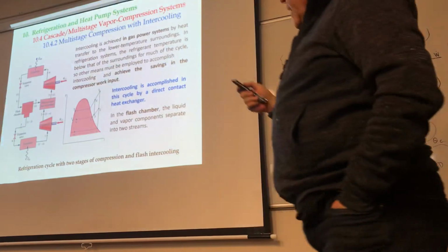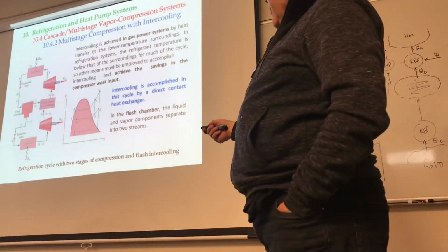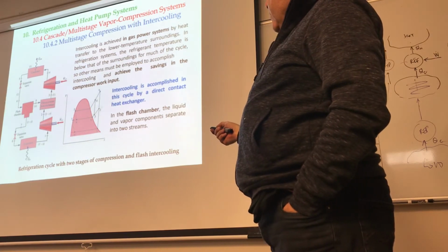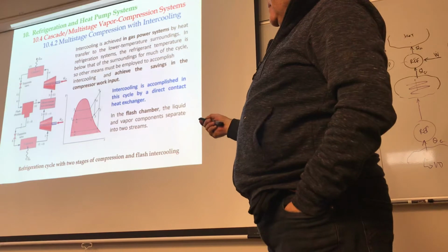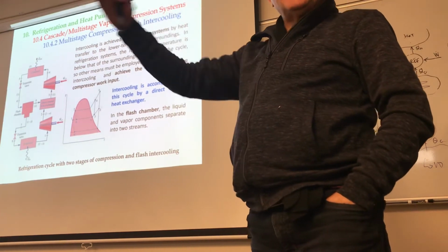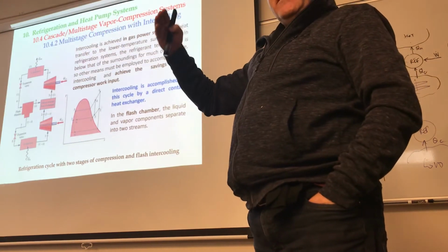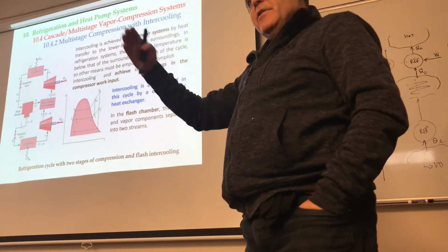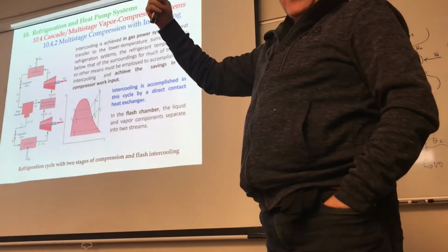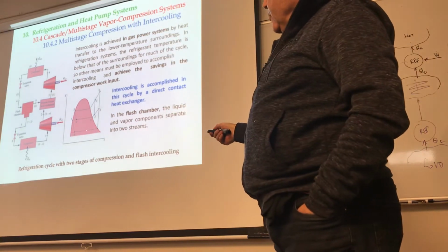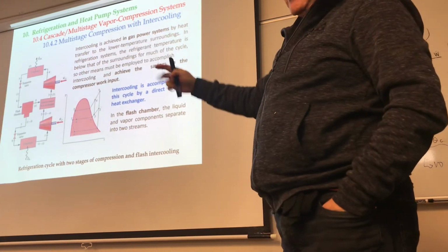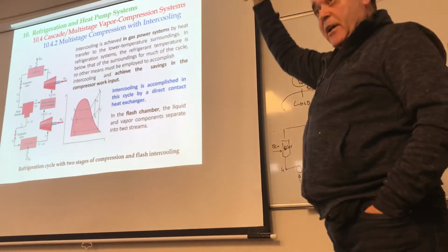Now, in here we're starting, let's say, from 1 to 2, right? As you go from 1 to 2, remember, anytime you use many turbines, we call that multi-stage expansion. If you use many compressors, it's multi-stage compression, right? This qualifies as multi-stage, even though it's only 2 stages. So you are operating between the low pressure and high pressure. Anytime you have multi-stage, that means you have some intermediate pressure in between. In other words, you're not compressing directly to the higher pressure.